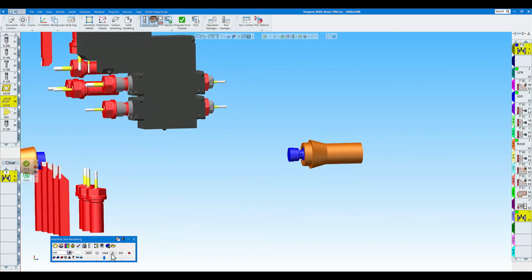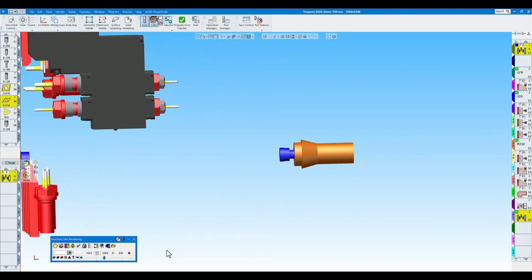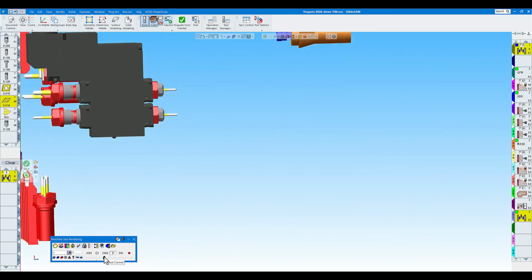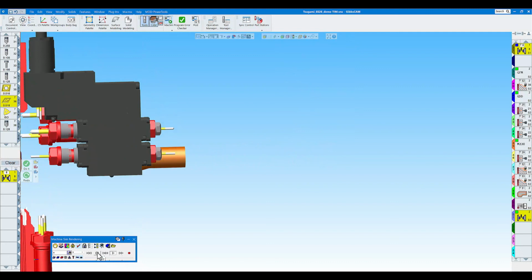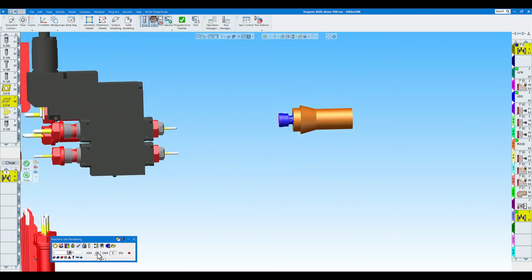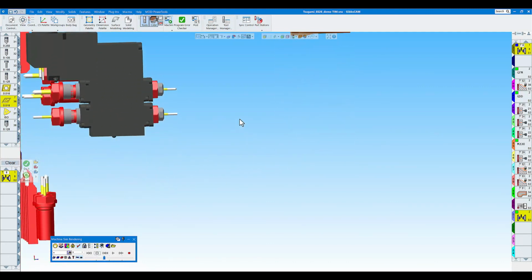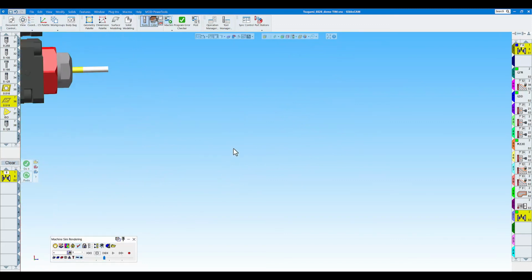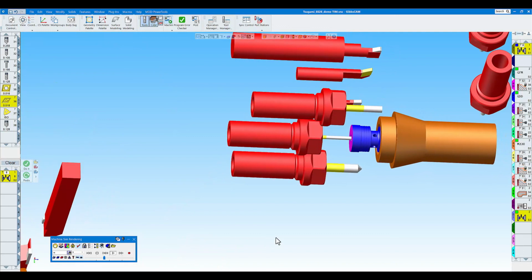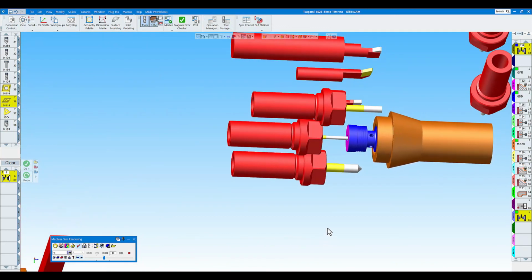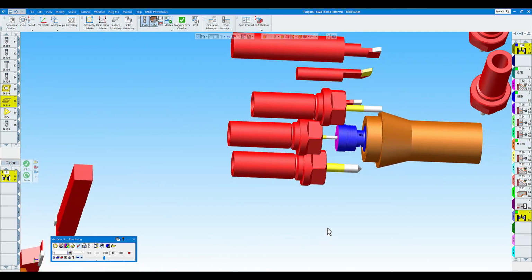Now if I rewind and just show you what the sub spindle is doing. Of course we're facing off up there, then it comes over, simultaneous drills. Then we're going back up to where it will be actually on the machine. A little bit better there. Okay, so now you can see we're drilling that long 100 thousandths drill pretty deep.